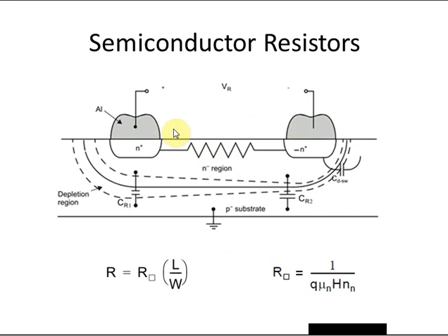Some key points about N-well type resistors. Generally, they have a lower resistance per square than polysilicon resistors that are made without the salicide applied. So therefore, they're more useful for making resistors with values in the range of, for example, tens of ohms. 50 ohm termination resistors are one typical application of N-well resistors, simply because the resistivity of polysilicon is so high that it would take many, many strips in parallel to get a value of 50 ohms typically.